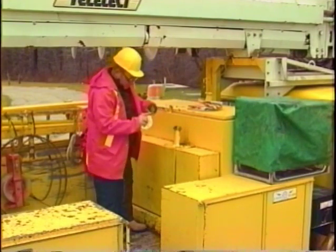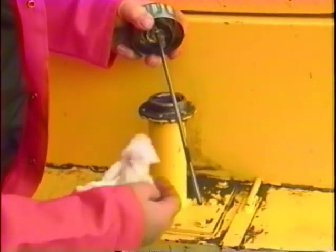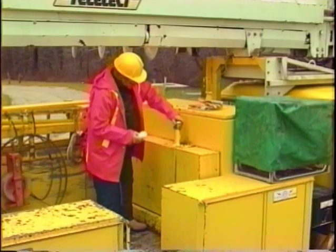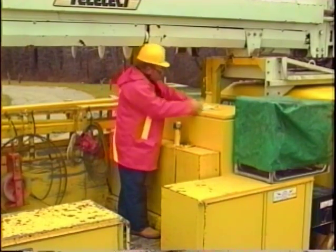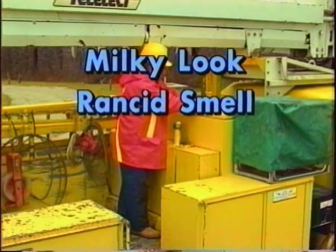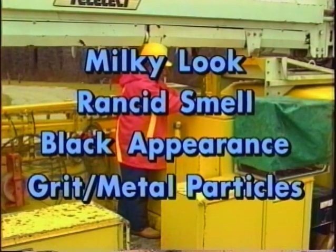Now it's time to check the condition of the hydraulic fluid. The importance of this step cannot be overstated. One manufacturer claims that as many as 70% of all service problems could be avoided by more frequent fluid changes. Some things to look for are a milky look, indicating the presence of water, a strong rancid odor, giving evidence of overheating, a black appearance, or the presence of grit or metal particles.